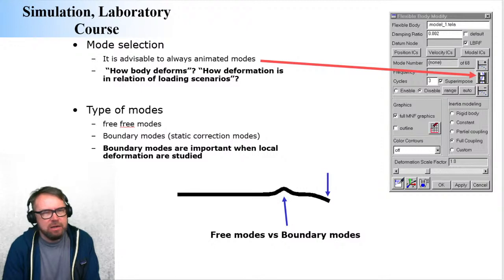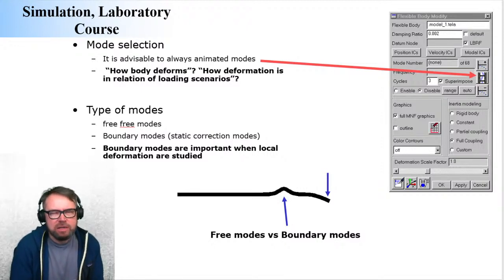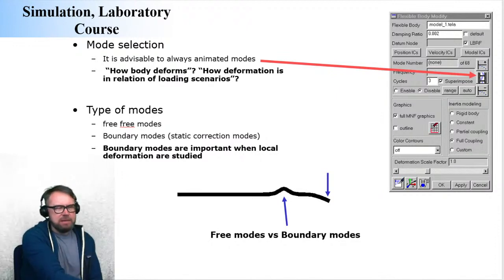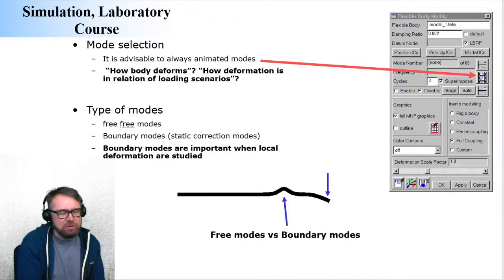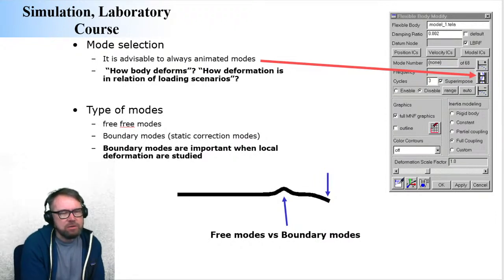You need to look at what possible deformation could be introduced by your forces in your structure. This is a simple case: if you have all the forces in plane, like a crane that can only move in a planar motion, then it makes little sense to introduce off-plane deformation modes. You can have one or two, but don't take more than that.